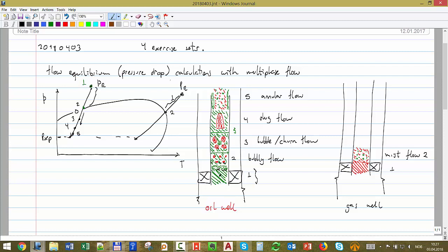Okay, you start getting the first droplets condensed out of the gas, and then you start again the same procedure, that you have this annular flow. When the liquid starts getting enough quantity, it starts accumulating at the wall, and you have more droplets transported in the center.